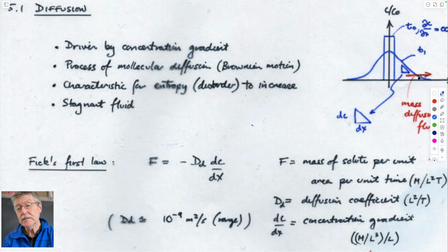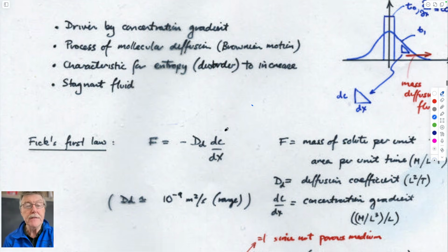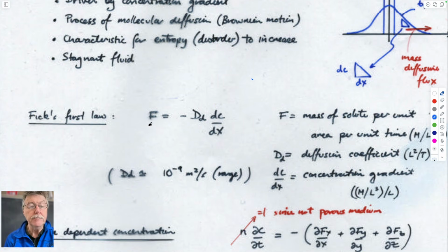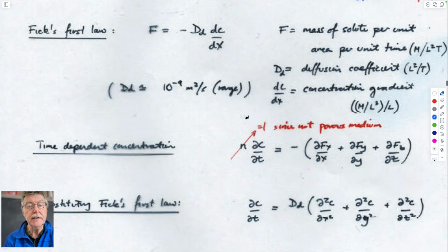The mass flux is the dissolved pigment in the ink that you put in, and it conforms to Fick's law in that this is the mass flux, this is the diffusion coefficient, length squared over time, meters squared a second, and the gradient in mass per unit volume, typically, and a length over which it travels. So this is mass per unit volume, milligrams per liter, or kilograms per cubic meter, whatever it is,